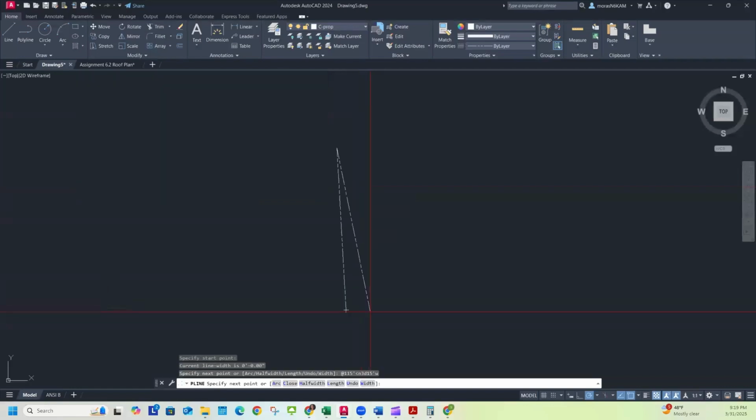Okay, and so now it made that line 115 feet long, and it's going north from this point, and it's going this way, and then it's going to be 3 degrees and 15 minutes turning west. So instead of going straight up, it's going to turn slightly towards the westward direction.